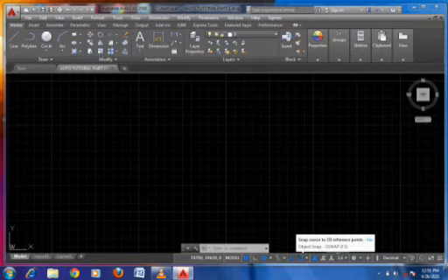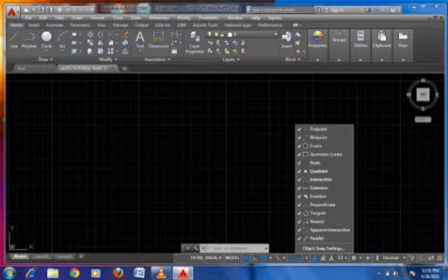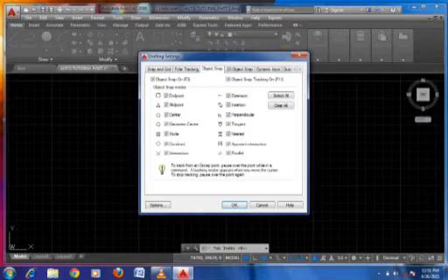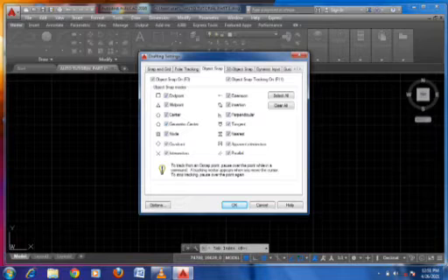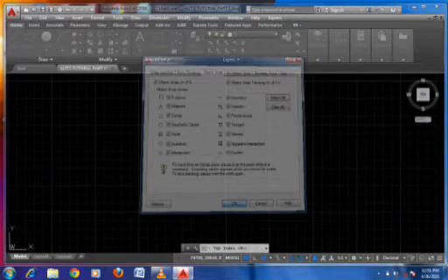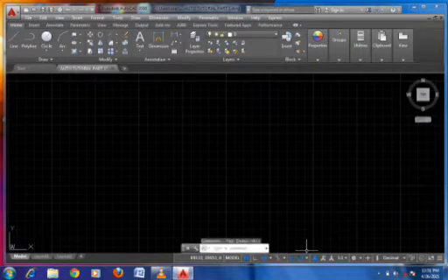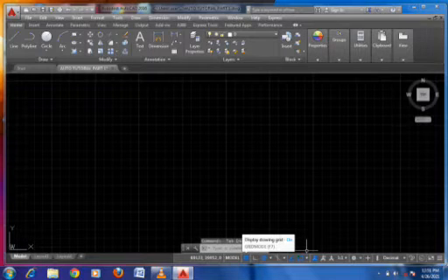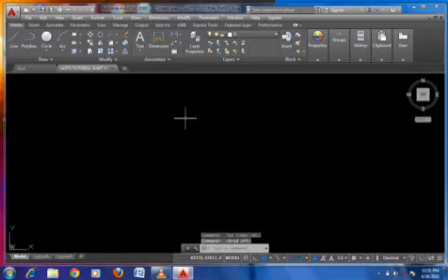It's like a tracking property. Everything in my object snap setting, I put everything on so I can track any point I want to access on my modeling. I click on OK. So it is on. Now let's turn off our grid line. I've turned that off.